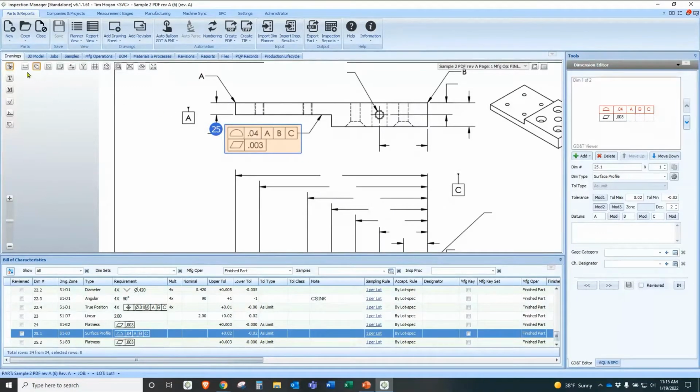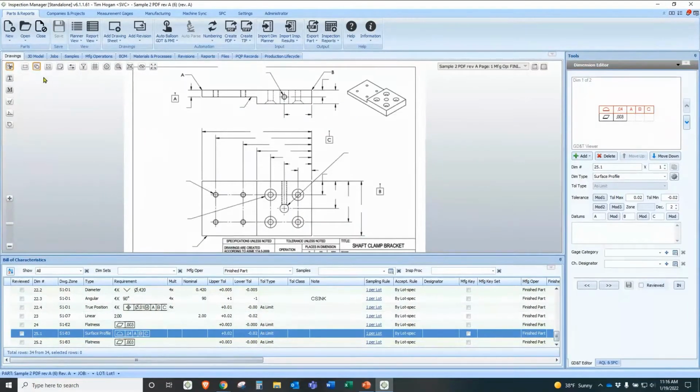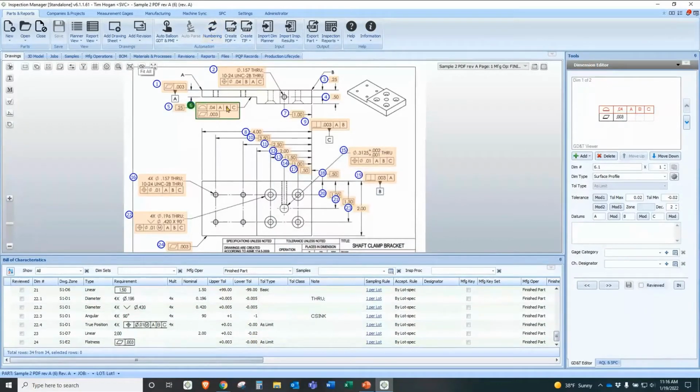And we can turn off the whiteout, and now we can see that it has all the dimensions listed. And now we can come over here. Now we're out of sequence, right? Because we deleted the number 6 and then we added another one, so it doesn't realize it. It's not going to automatically populate number 6 because it doesn't know if it should or not. So we can simply come up here to renumbering, and it renumbers it, puts it back in order, just like we'd like.